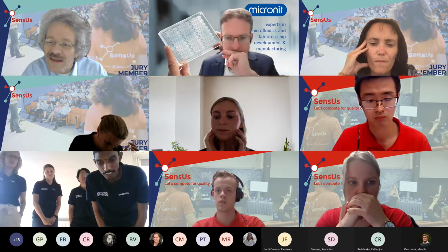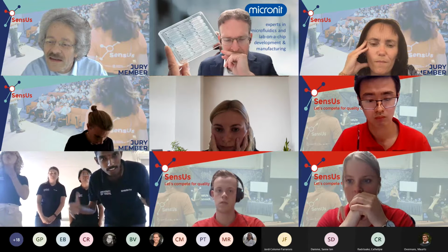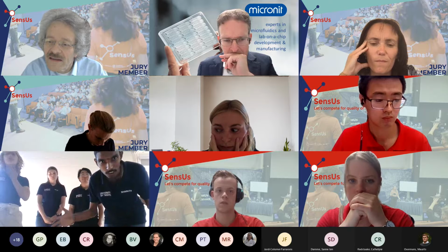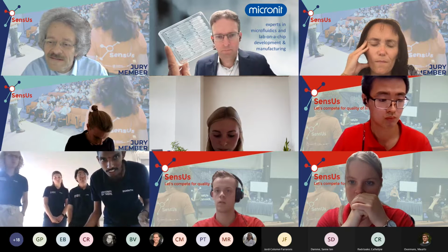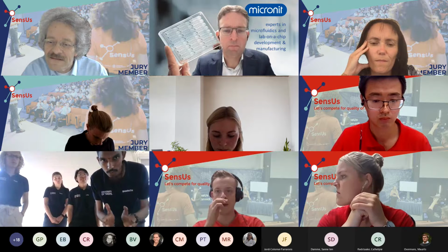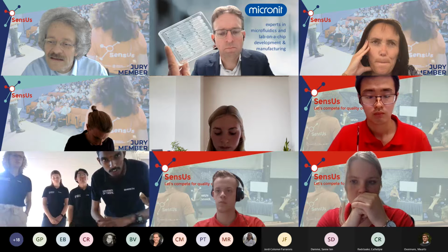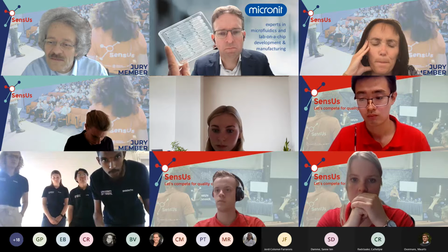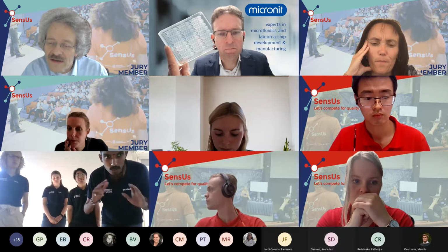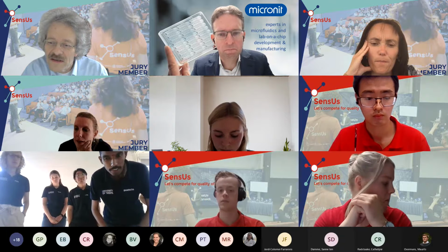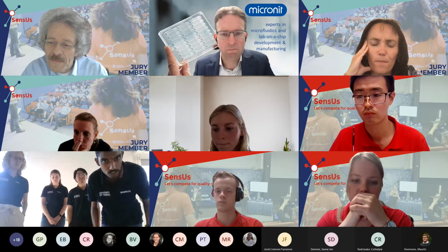Yeah. Actually, we just selected this particle range because if we select some bigger particles, they may occupy a large space inside the channel, so we might lose some of the antigen detection itself. If you go for smaller particles, they may get attached almost homogeneously on top of the surface. So there's a possibility that we can go more sensitive and lower the limit of detection. We can go up to a few hundreds of femtogram per ml as the concentration.